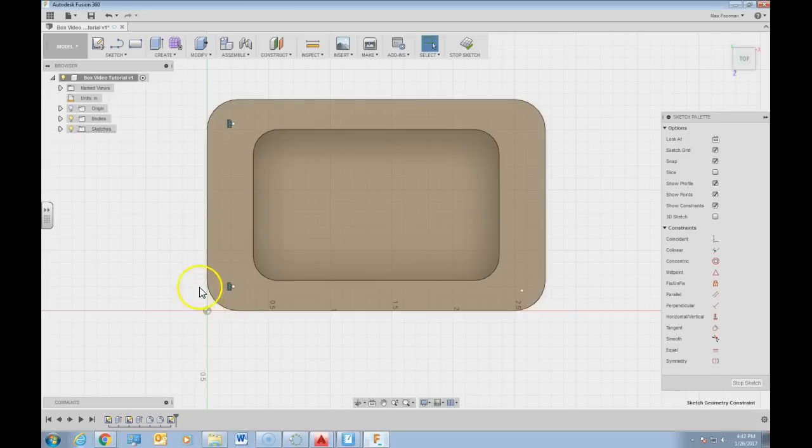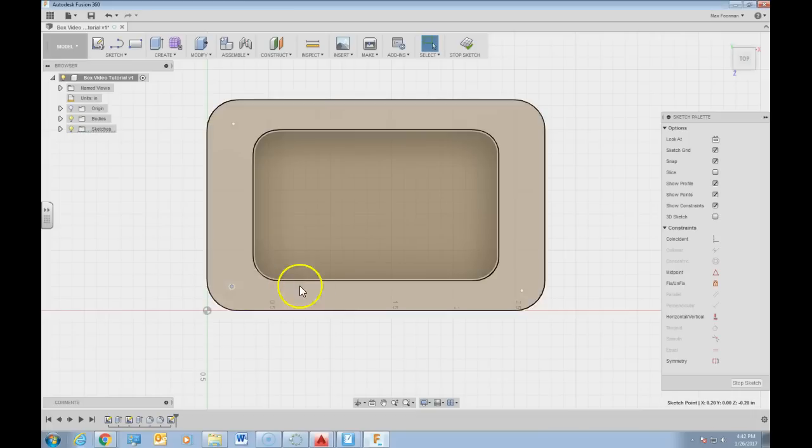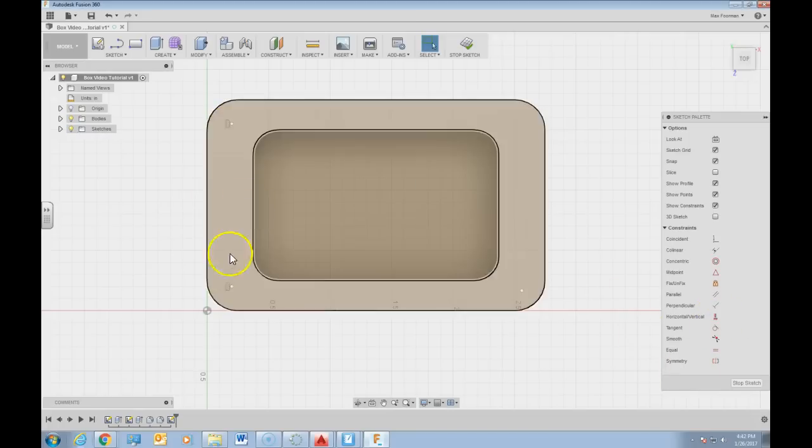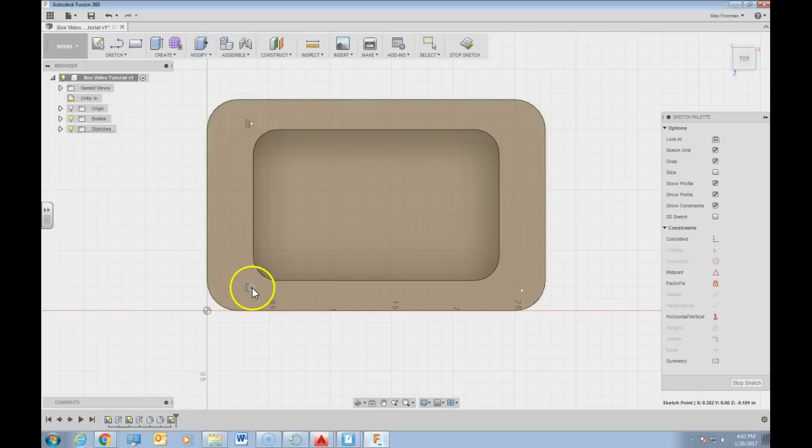If I made that incorrectly, I could click on that icon there and delete those. Now if I click and drag, that happens. But no, I really did want to have that, so I'm clicking that point, vertical to that point. Same deal, but see how it pulled this point in line with that one. Now if I click and drag these things, if I move this one left and right, the other one follows along. And opposite of that, click there and there. So now these things are vertically aligned and have a relationship that keeps them in line with each other.